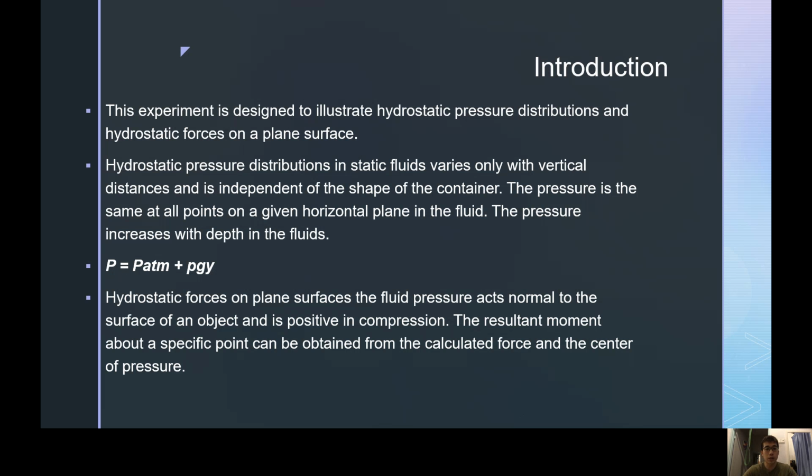Hydrostatic forces on a plane surface. The fluid pressure acts normal to the surface of the object and is positive in compression. The resultant moment about a specific point can be obtained from the calculated force and the center of pressure.